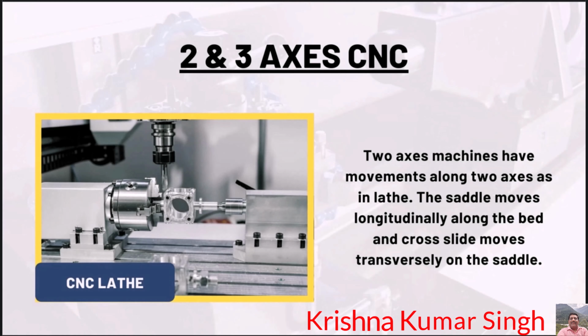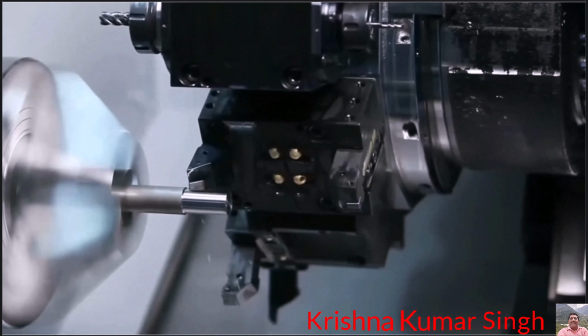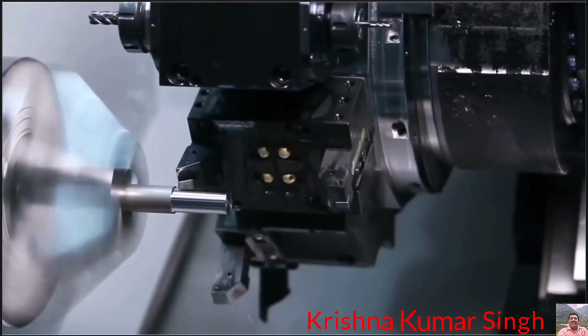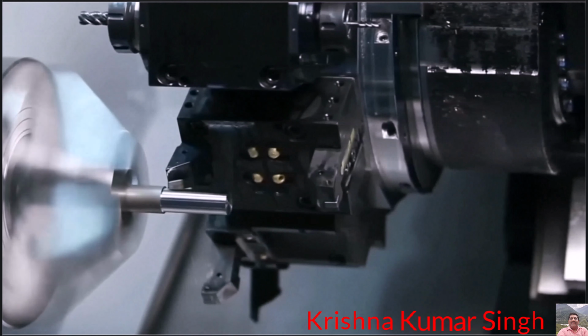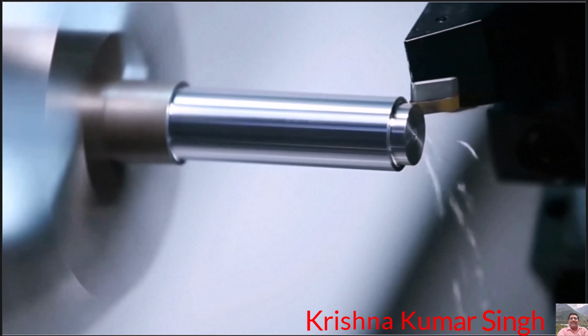There is one more type of classification for CNC machines, that is based upon axis. Let's discuss 2 and 3 axis CNC machines. 2 axis machines have movements along 2 axes, as in a lathe. The saddle moves longitudinally along the bed and the cross slide moves transversely on the saddle.